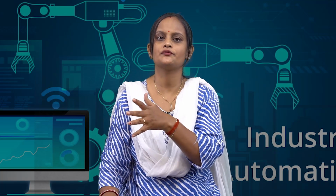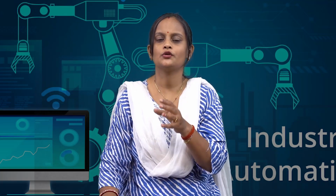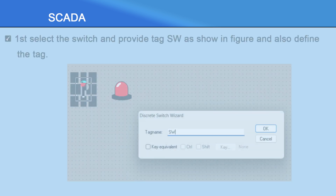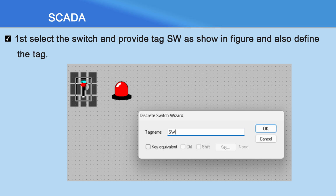You have to click on the wizard option, various options will appear, then you have to go to the switch, and the different types of switches will appear, then you have to select which type of switch you want. Similarly for the light, you have to click on the light indicator, and all sorts of light indicators will appear, and you have to select which light indicator you want. So I have selected one switch and one light there. When you click on the switch, it will ask for the tag name. I have added SW as the tag name of my switch.